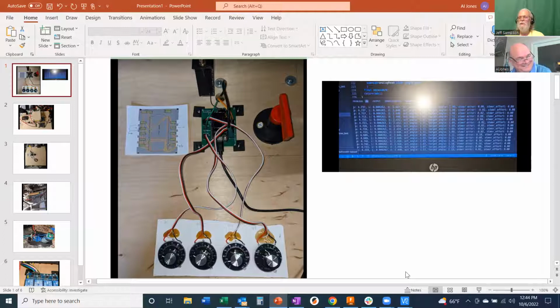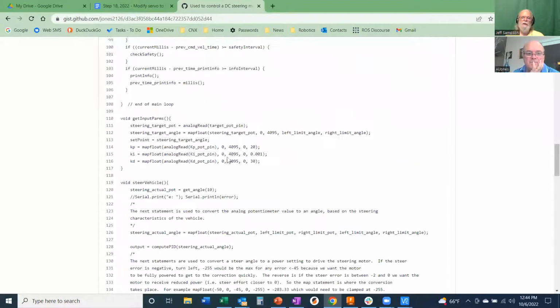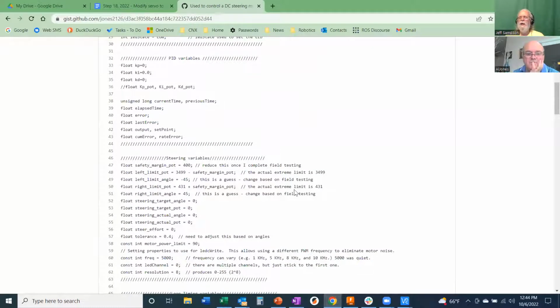The reason I ask is because if you have a high impedance A to D input, like on the Arduinos that have the Atmel AVR, they have like a 1 megaohm input impedance. So you can put just about any pot you want on there, though don't get too large of a value. But when you switch over to the ARM parts instead of the AVR, their A to Ds work differently, and somewhere it says they're an equivalent of like 3K ohm input impedance. So you might have an electrical issue there besides just picking up noise from the motor. It could be that on the ARM parts the A to D doesn't work as well.